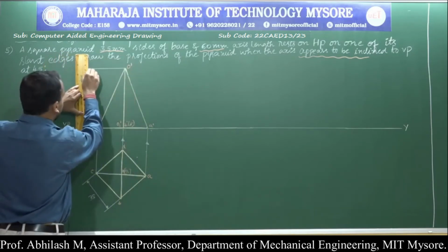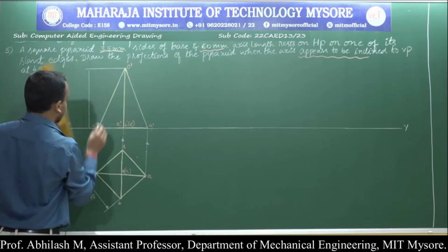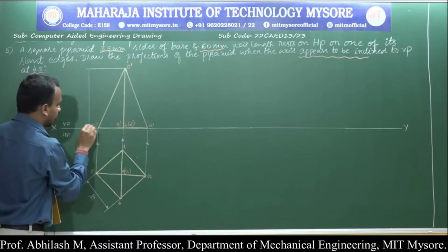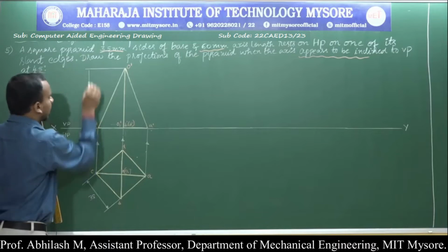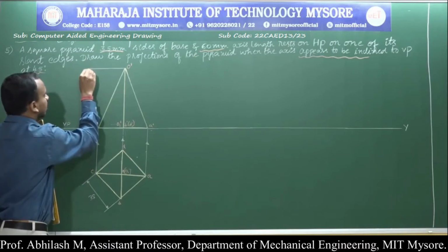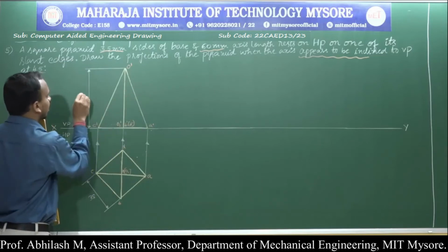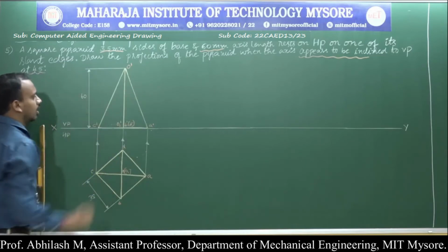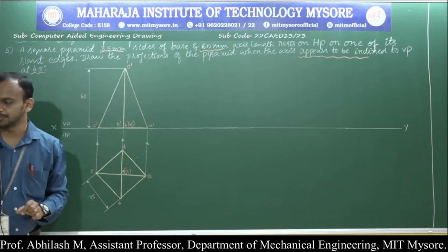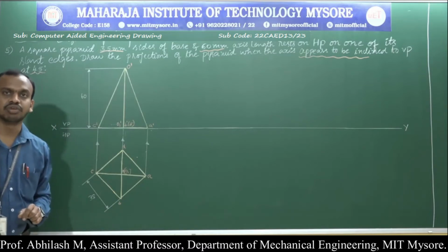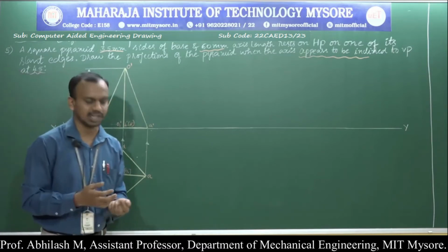Dimensioning is very important in engineering graphics. So just draw the line with filled arrows and highlight the axis length that they have specified. The axis length they have specified is 60 millimeter. So draw 60 millimeter. So we are done with the first position for the given condition.